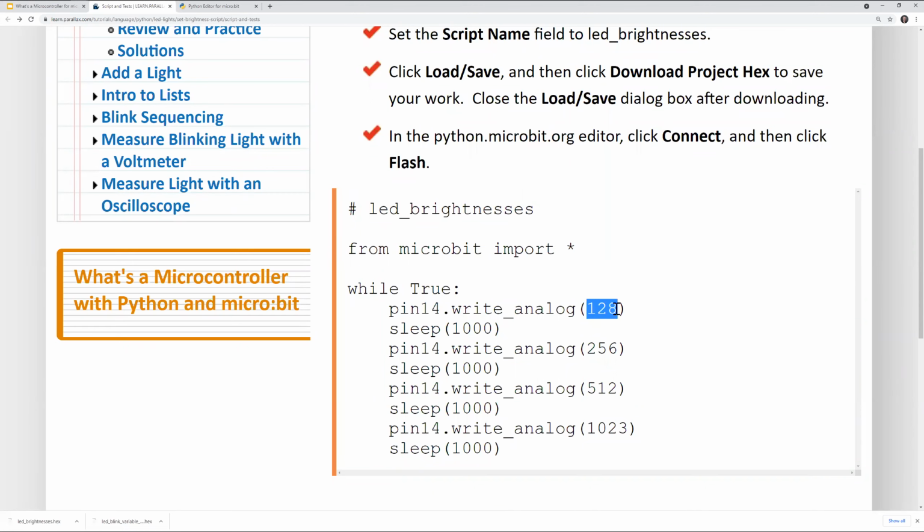Now, when it says 128, that's 128/1024 of that 50th of a second, it'll stay on. 50 times a second, so it's not something the human eye can actually detect as flashing. The limit for that is, well, it varies with color and intensity, but it's generally accepted to be a little under 30. Old analog televisions depended on that fact.